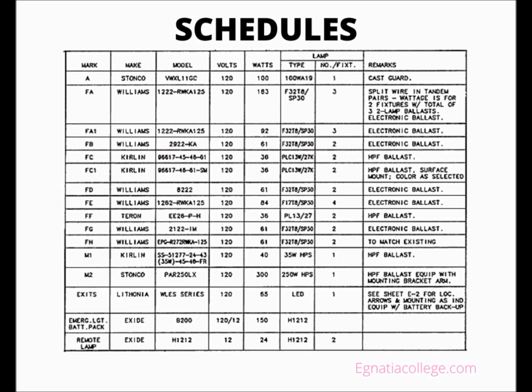The local plans review and the utility company typically require a connected load schedule. This type of schedule includes type of load, building or area designation, size of load, kilowatts or horsepower, total electrical load by type or area. Notes explaining any special methods used in the load calculations.